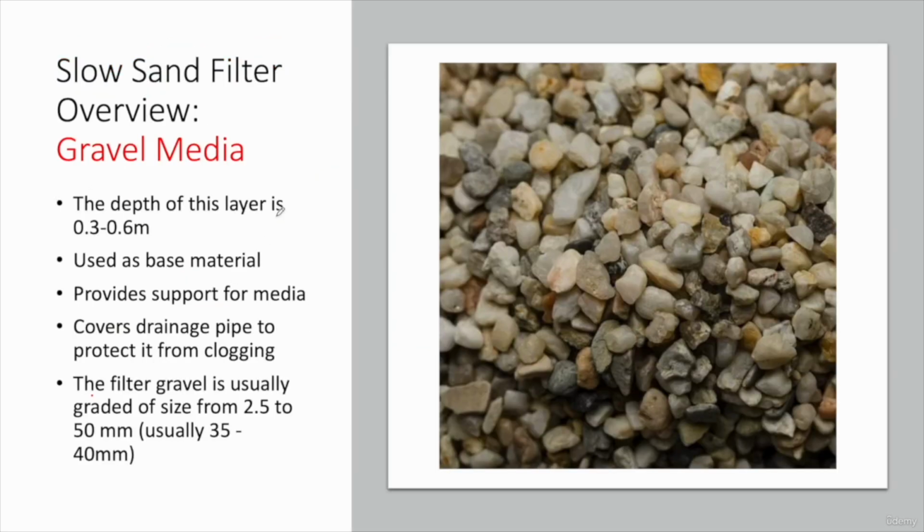We will go through the media quickly. We have two types of media, as we have said, gravel and sand. The depth of the gravel is 0.3 to 0.6 meter, used as a base material. It provides support for the media.